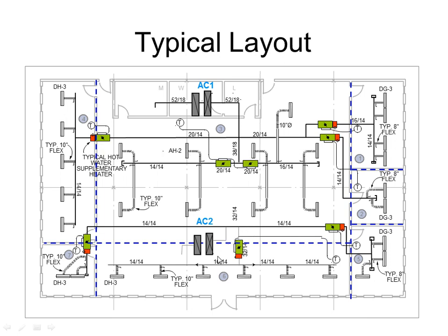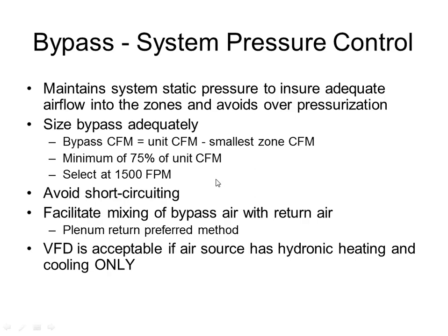The same thing happens on the bottom zone because of the sun exposure, you've got your east and your west, but you always want to have your south zone separate from the rest of the system because your south zone is always going to be exposed to sunlight, and because of that, you're generally going to have a cooling load or cooling call. So just a general little layout here.